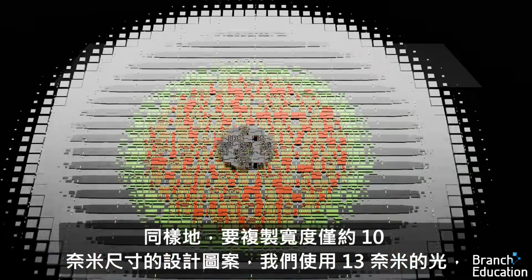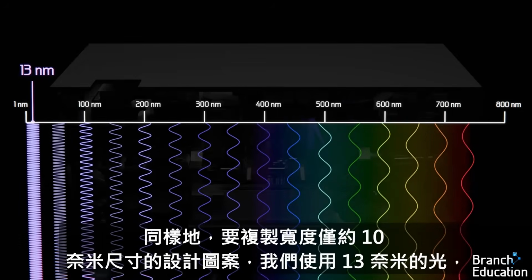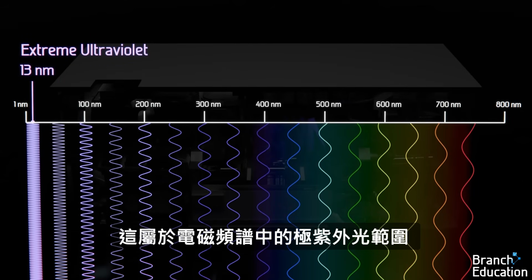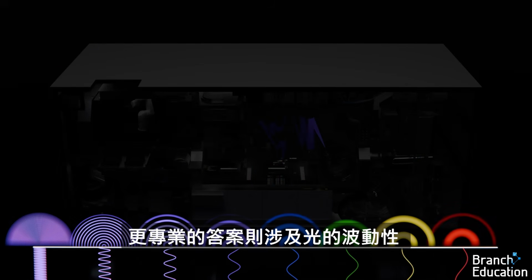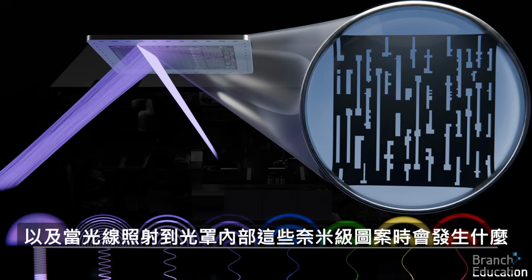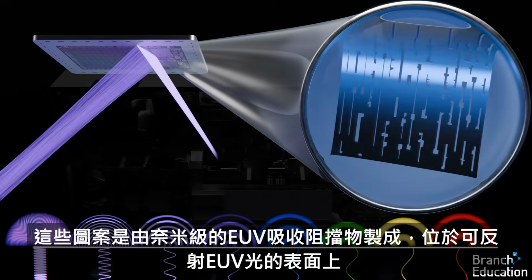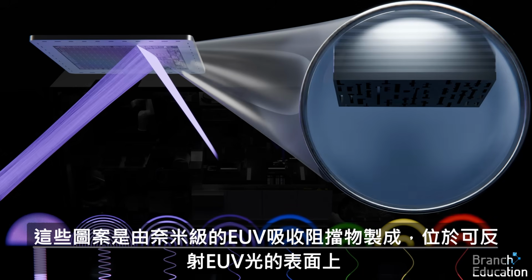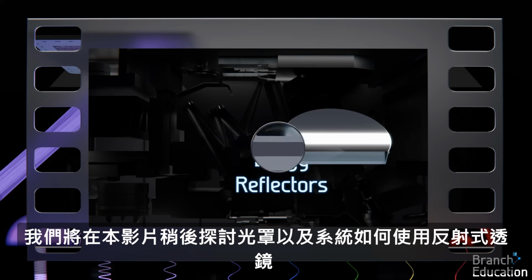Likewise, to copy designs with dimensions only around 10 nanometers wide, we use 13 nanometer light, which is in the extreme ultraviolet light range of the electromagnetic spectrum. The more technical answer deals with the wave-like nature of light and what happens when light hits these nanoscopic patterns inside the photomask. These patterns are made from nanoscopic EUV-absorbing blockers on top of a surface that reflects EUV light. We'll explore the photomask and how the system uses reflective lenses a little later in this video.